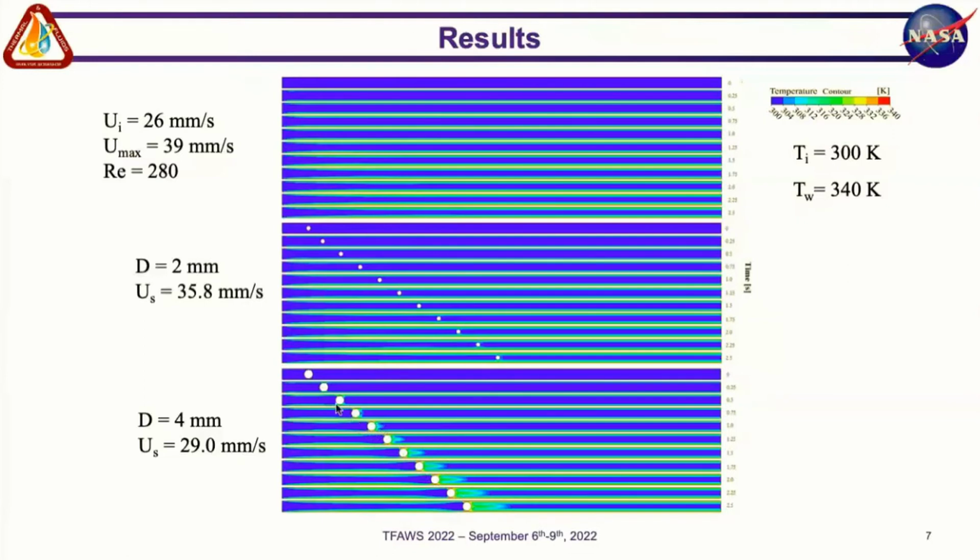Upstream, you have the tendency of the particle dragging the cold fluid that's coming in a little bit deeper down the channel. So that should have an effect on the heat transfer process. And the other thing that we notice is this change of colors downstream of the particle that indicates the fluid in there is heating up. The temperature is higher, is increasing. And that means that your particle is pretty much sweeping or pushing the fluid downstream. And of course, that fluid includes the fluid close to the wall that's heated by the wall. So you're essentially pushing this hot fluid out of your channel. And this, of course, is expected to have an effect on your heat transfer process.